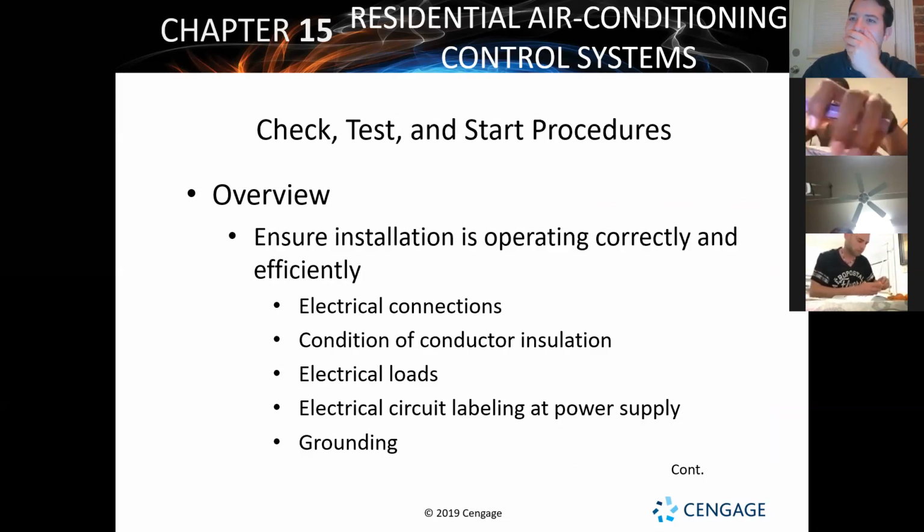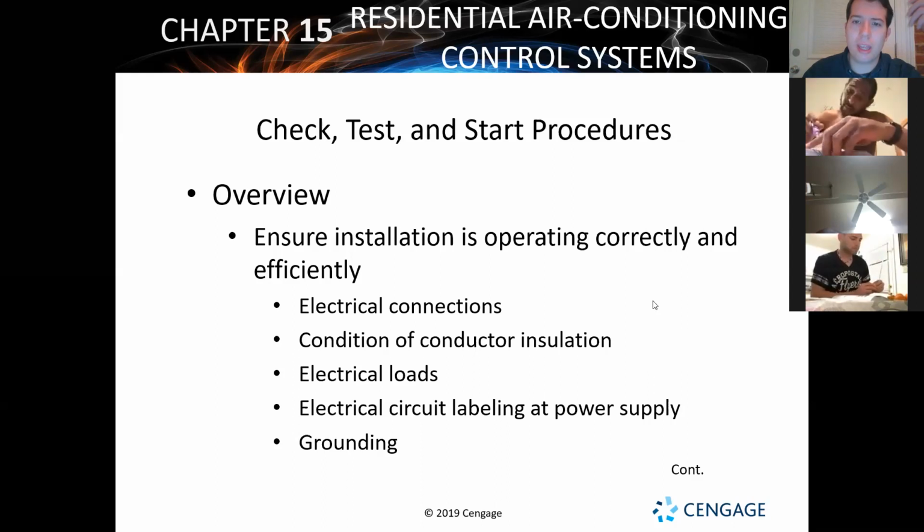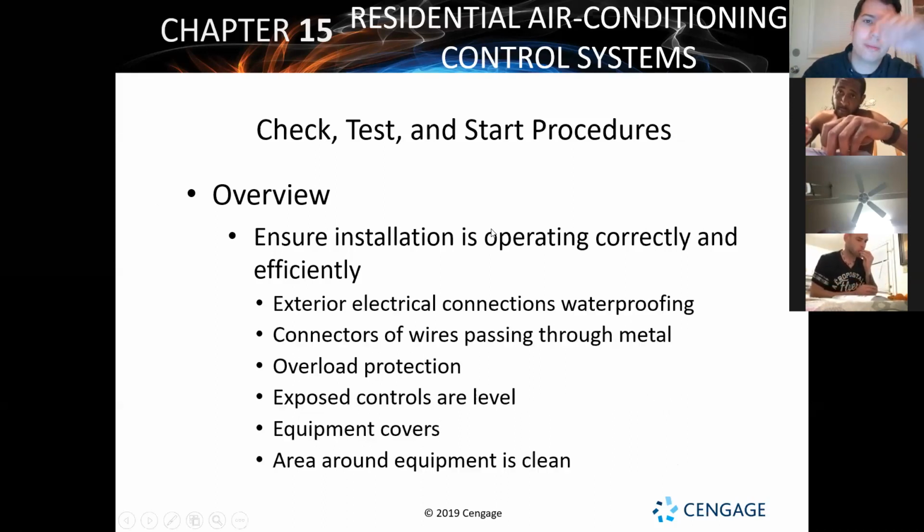So system startup is typically going to be right when you finish installing a unit and you've got it first starting up. That's what you're going to be doing, as well as any time that you do a repair or replace a component or a part, or anything like that. You're going to be doing a system startup check to make sure that the system is working properly. Whether it's your blower motor you're checking, just like we were in those simulations. Last thing we did, close everything up, turn everything back on, sweep up behind ourselves, make sure everything's doing what it should.